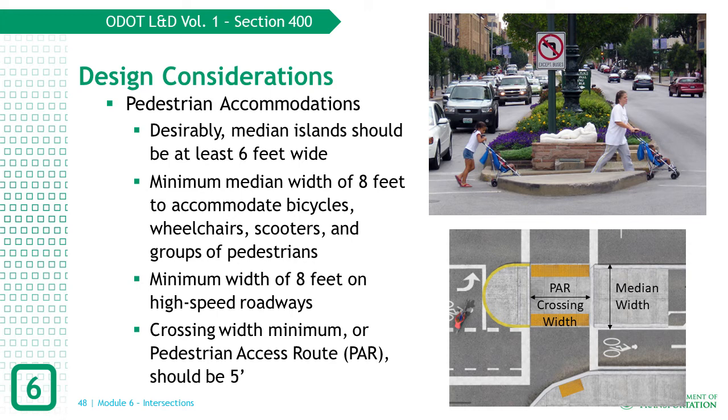In intersections with long crossing links, confirm the amount of time a pedestrian requires to cross the roadway. If the necessary crossing time negatively impacts overall intersection operations, it may be necessary to create a 2-stage pedestrian crossing requiring a pedestrian push button within the median.